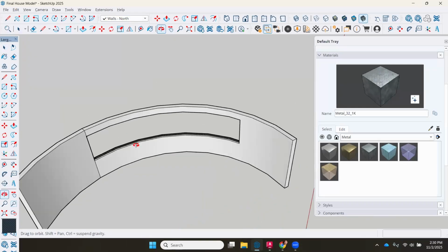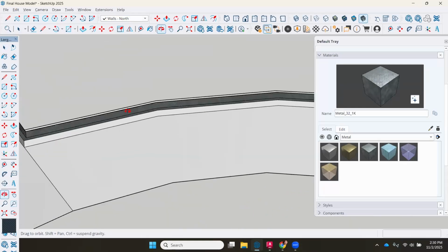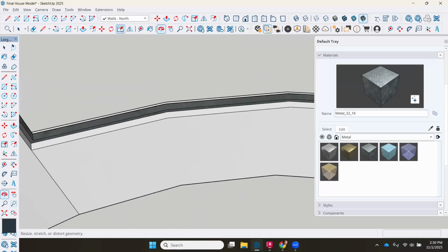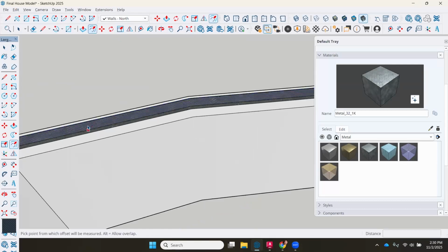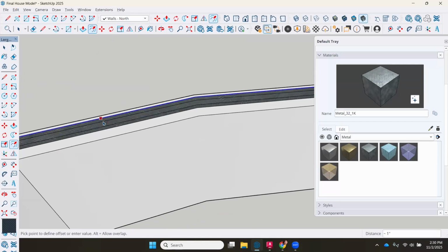So far, next is putting in the glass panes. Same idea. We're going to offset now from this frame here. Glass can be made really thin, but in this house, you probably want it double paned too, just for holding the heat of your house. So again, I'm offsetting from this line here and then pulling it in, and I'm only going to pull it in a half inch.